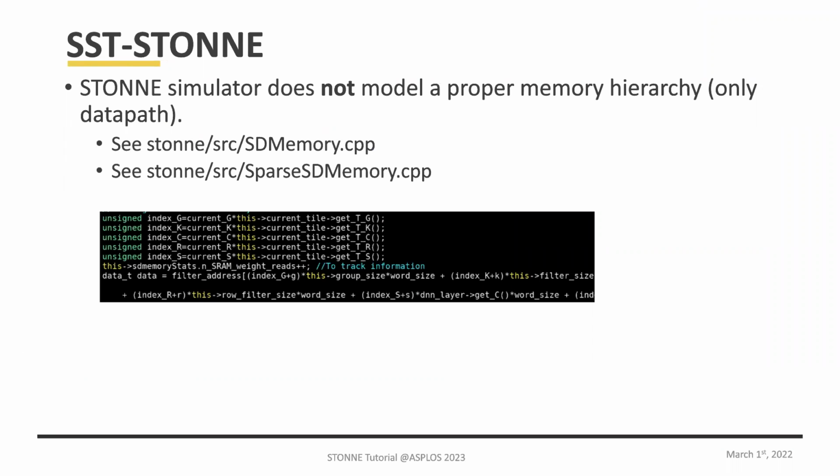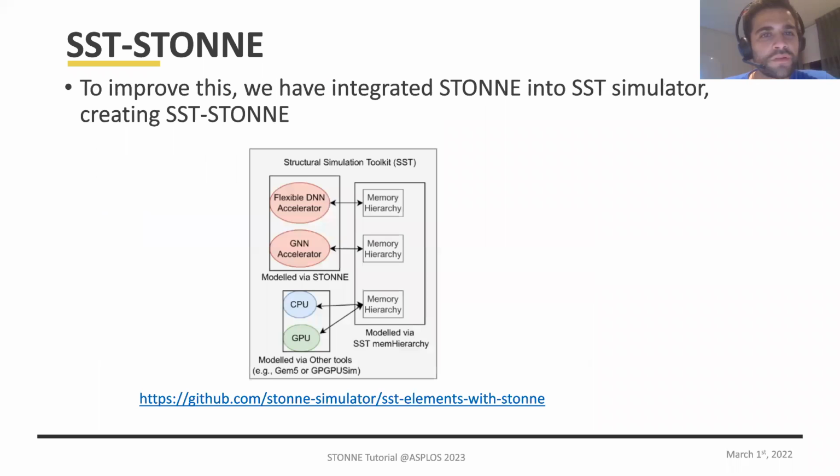Thanks. Okay, so as I was saying, the memory hierarchy is not modeled in the version of STONNE I just showed you. So for that reason, we integrated STONNE into the SST simulator, creating SST-STONNE. SST, the Structural Simulation Toolkit, is a simulator from Sandia Labs, a whole environment to include more simulators.